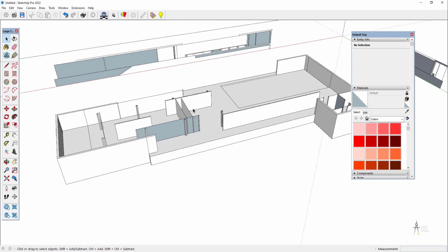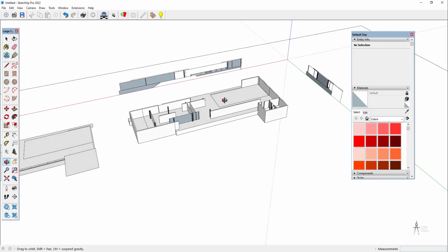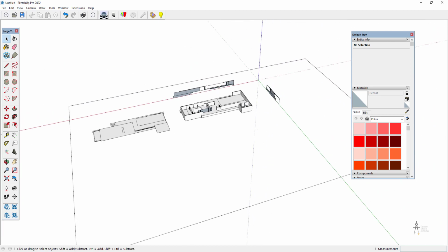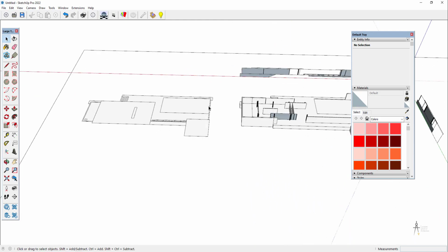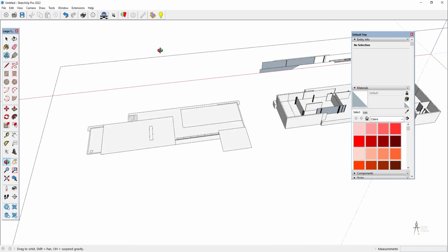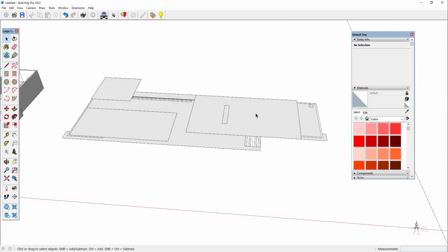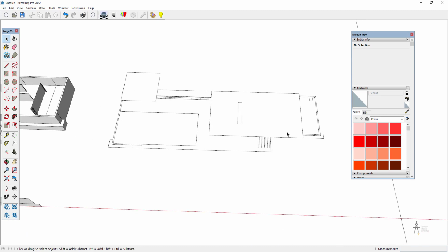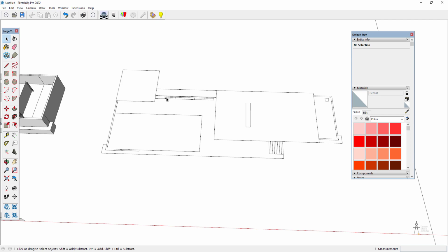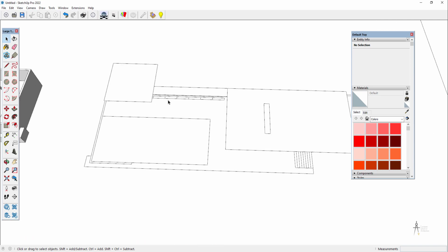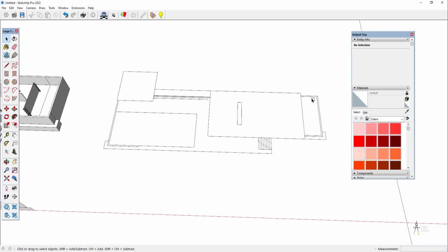Okay, so now that we have our pillars created, it's time to finish off with the roof. If you check out the roof, you will realize that there are a lot of projected lines, and well, you could have sorted this out in AutoCAD, but you can do it now. All of these elements are projections, and we don't want to extrude or create models out of them. So what we're going to do is erase them here. Again, you could have done it in AutoCAD.